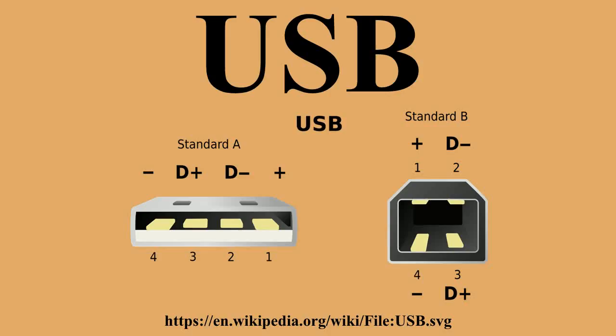The 24-pin double-sided connector provides 4 power-ground pairs, 2 differential pairs for USB 2.0 data bus, 4 pairs for high-speed data bus, 2 sideband use pins, and 2 configuration pins for cable orientation detection, dedicated as biphase mark code configuration data channel, and VCONN plus 5V power for active cables. Type A and Type B adapters and cables are required for older devices to plug into Type-C hosts. Adapters and cables with a Type-C receptacle are not allowed.